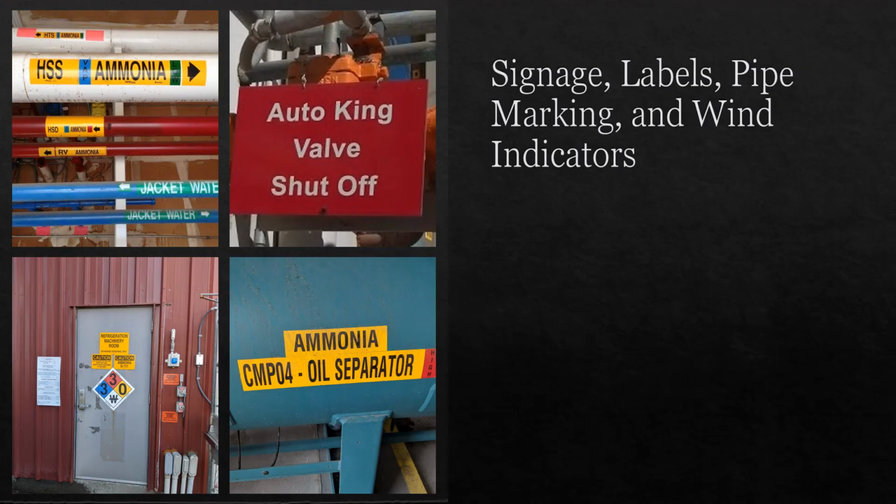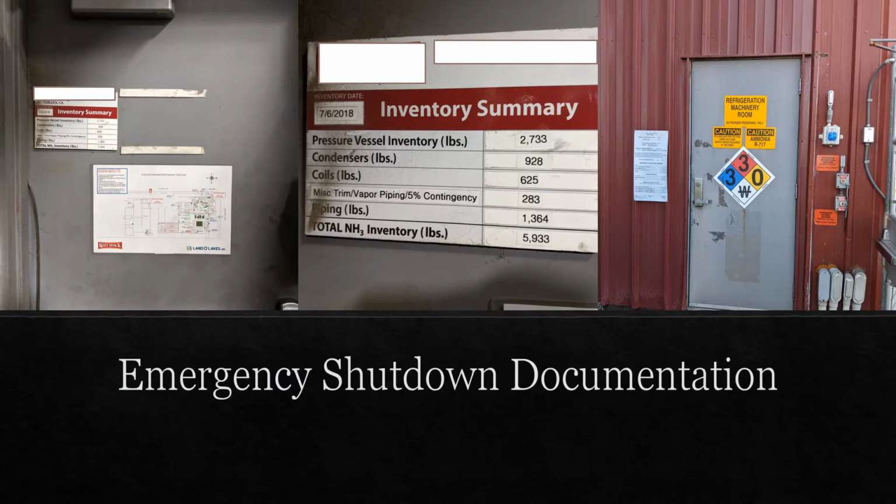With regard to signage and labeling, Standard 9 closely matches Standard 2. Machinery rooms must be equipped with NFPA 704 placards, alarm signage, and restricted access signage. Equipment must be provided a label indicating the equipment ID number. Valves intended for emergency shutdown must be clearly and uniquely identified at the valve and on schematic drawings. And finally, all pipes must be labeled.